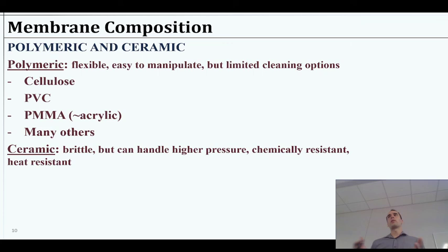So we have to be careful with how we design them to deal with pressure. There are some good membranes that can handle high pressure, but there's a lot of care that goes into making sure that they don't just go splat, right? And you can't bleach them too harshly, right? Because some polymers are going to react with the chlorine itself or whatever chemical cleaning agents you're using. Potential to oxidize the membranes or destroy them, dissolve them, that type of thing.